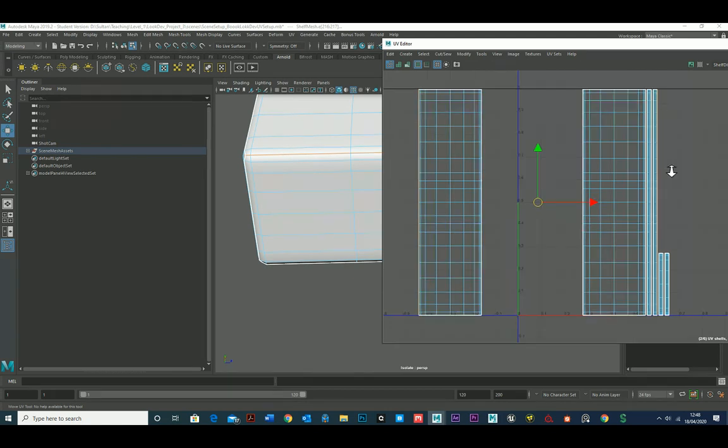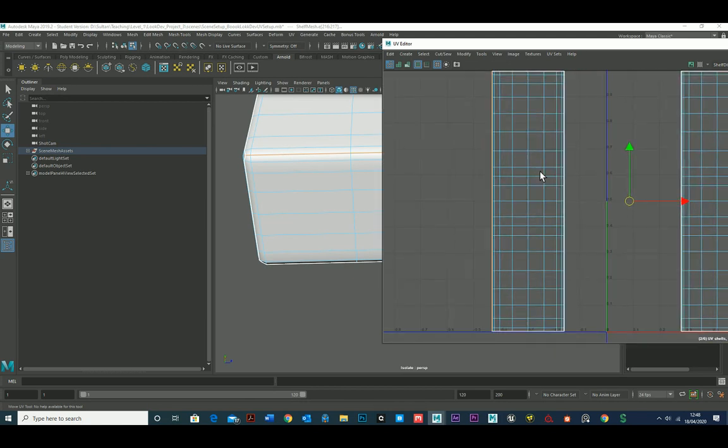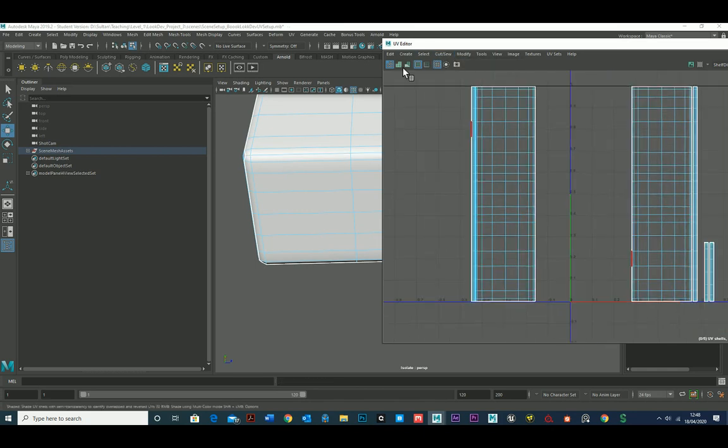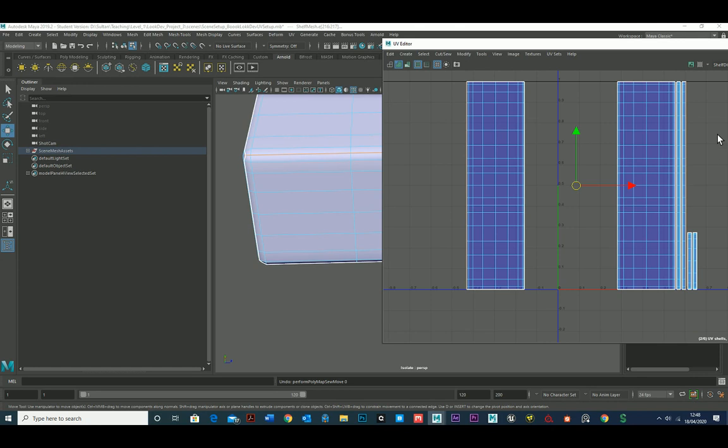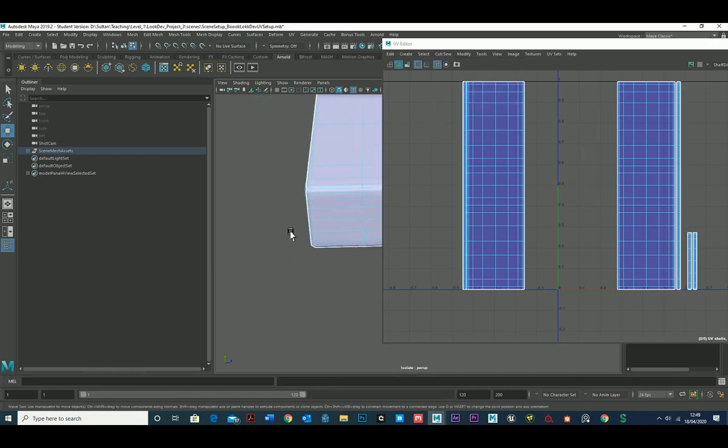In this case, there is something there you might not see in the video. You can see it's been highlighted. So I can go to cut and sew, move and sew. So now that piece jumped from here to there. So now we don't have any border edges there. We used to have a border edge there. Now it's all in one. We don't have one, it's continuous.